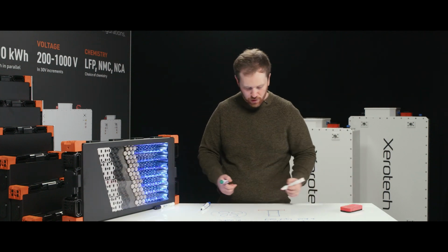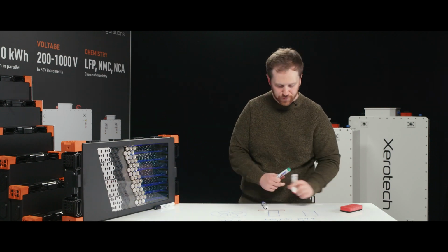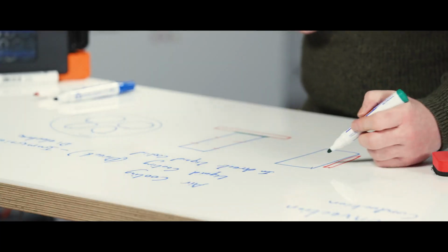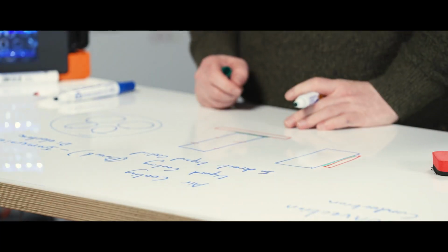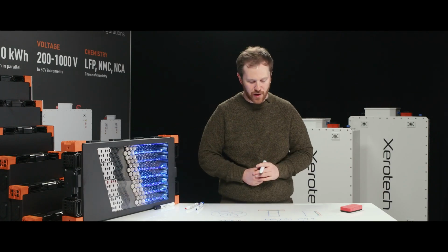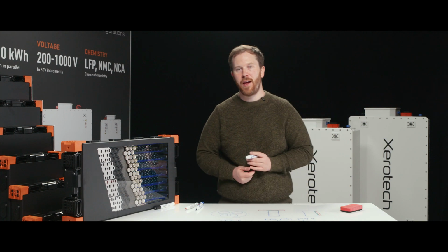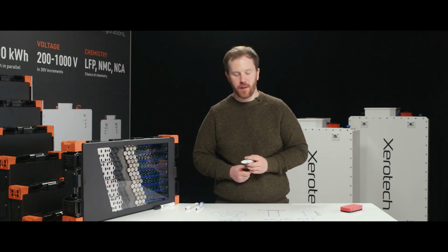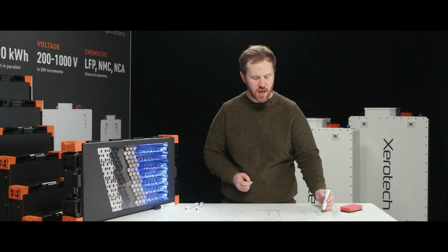There is another approach where you can cool the side of the battery cell, like so. The big advantage of sidewall cooling is that there's more area, and that's important because heat transfer, especially for conduction, is a function of area and temperature difference. The more area you have and the bigger the temperature difference, the more heat will flow.